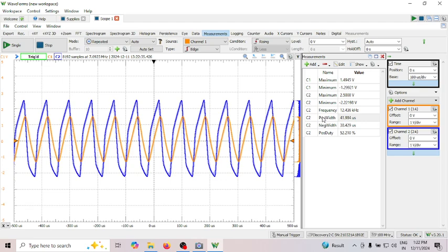Since you are expecting the waveform to be at very high frequency, which is not supported by the op amp that I'm using, you cannot get very high frequencies in this particular case. The 741 has a very bad slew rate, which is 500 millivolt per microsecond, which is very poor. So that's why you cannot use this 741 for generating very high frequencies.